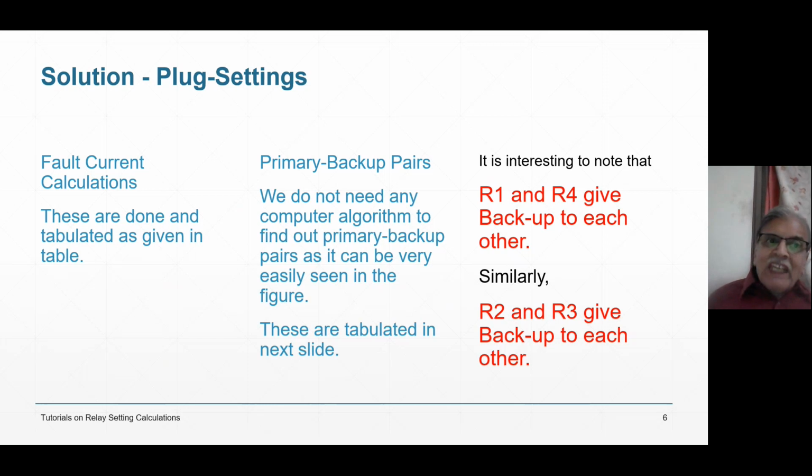with all lines working. Then the same fault location, one line contingency, meaning line number one contingency. Same fault location, line number two contingency, yet one line contingency. Line number two is different. Line number three, very difficult, very cumbersome. But here, my dear friends, we have only two lines, and one line contingency means very simple. So fault current calculations are not very difficult.